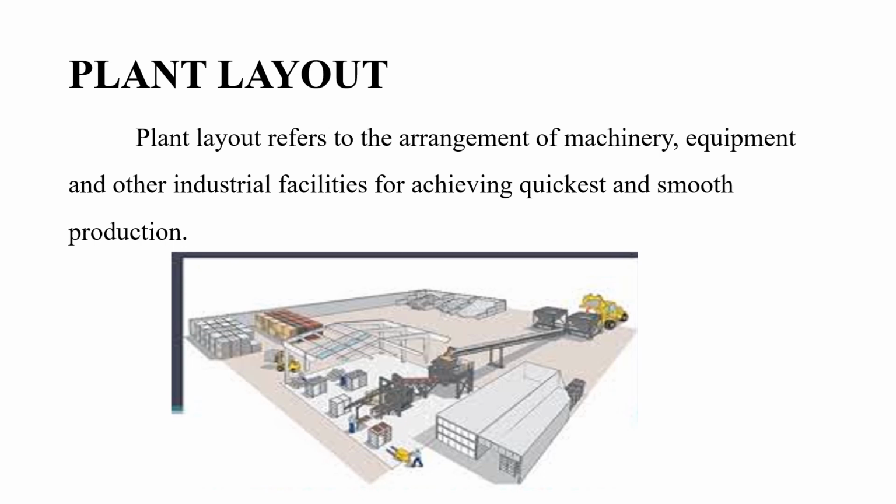After the plant has been located, the next thing we have to do is plant layout. You can see in the diagram, after the plant has been located, the next thing they are doing is locating the departments like tool rooms, maintenance wings, plating shops, heat treatment chambers, and the facilities for the employees like toilets and canteens. All the things should be located in a specific way so that it will be helpful in smooth production at least cost. All these things can be called plant layout.